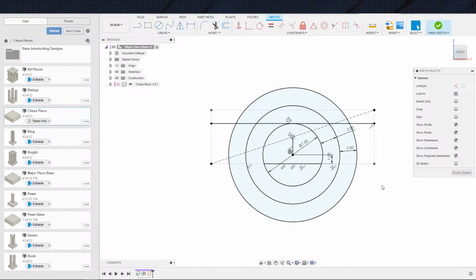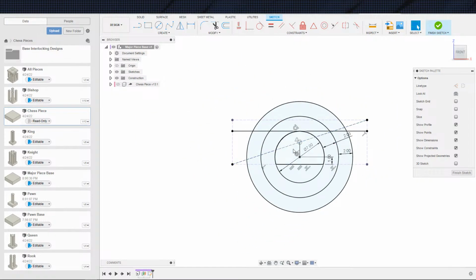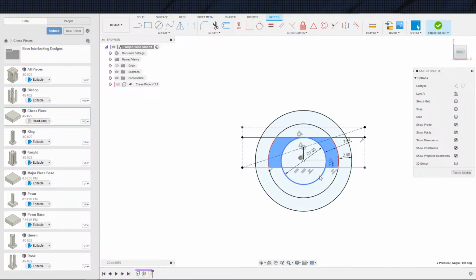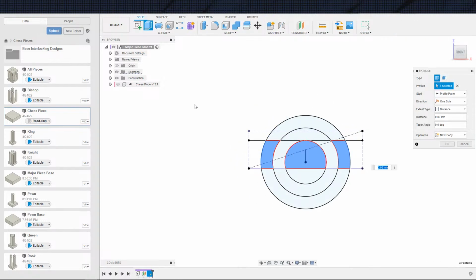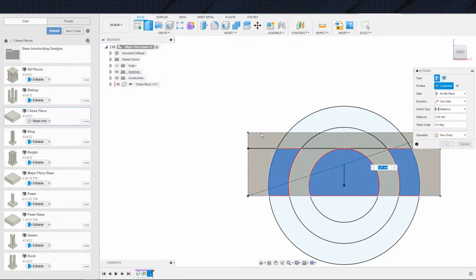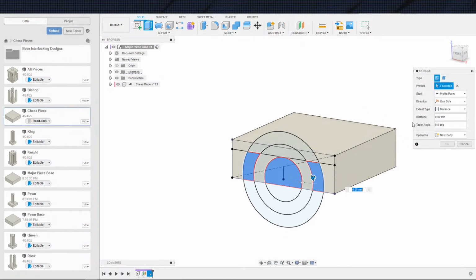This is just space. So looking at this, in case you can't read all these lines because they are weird, this right here, this inner one is going to be the clip. I'm going to go ahead and make this solid so that we select just this when we extrude. So that clip will get extruded. This right here will be empty space. That will be empty space, and actually because of that, I'll probably just extrude these instead, and that will give us a clip. It is not the prettiest of clips.